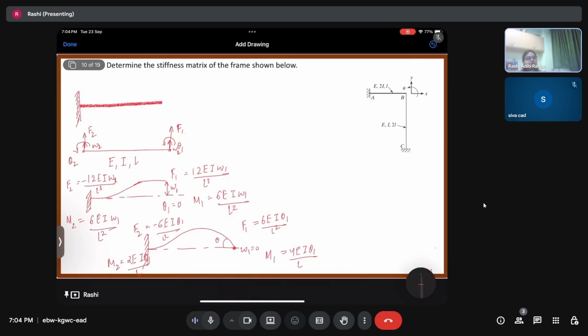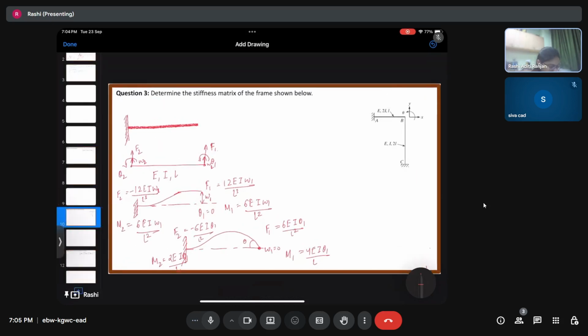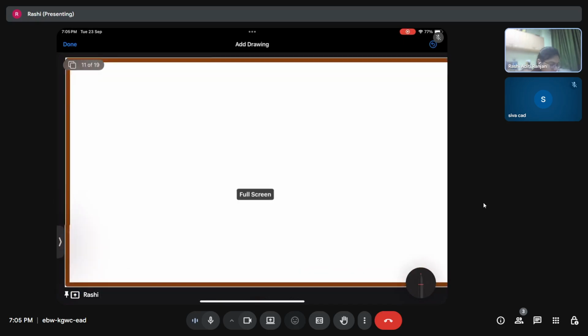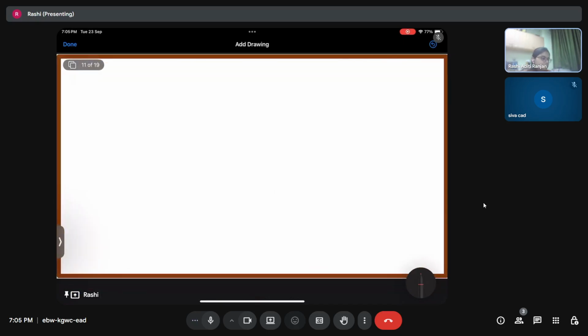Now we have to just apply it for our system. We have three directions, so we have to consider three unit displacements. One as x equals 1, another as y equals 1, and the third one as theta equals 1. So for the first case, we consider deflection along x, with x equals 1.